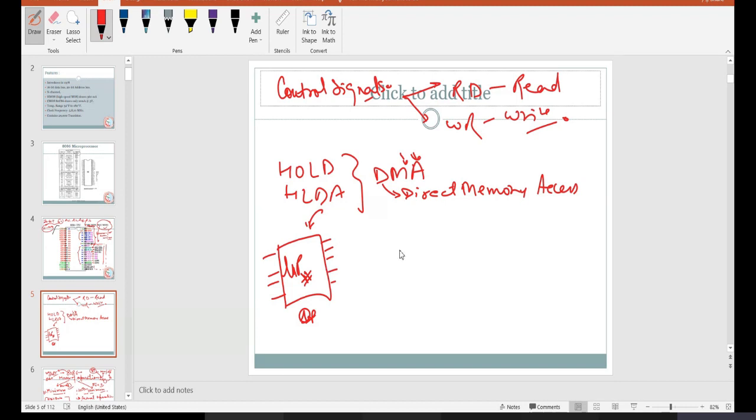Fine. And the step which is related with HOLD and HLDA is: if my control, or the control of my class, is going to be delivered to someone else, there is a step of communication. That communication starts with the HOLD signal. Let's think in a logical way. I'm delivering my class. Someone comes from the hold. This is not an interrupt signal. It is direct memory access.